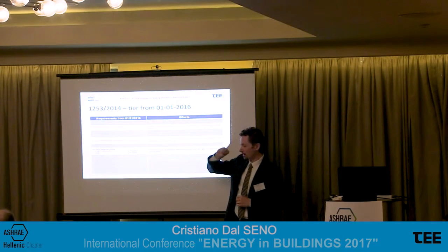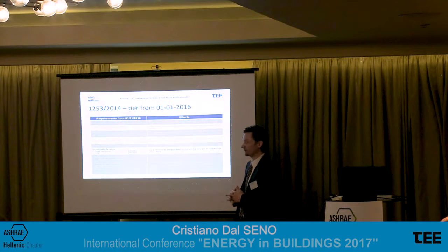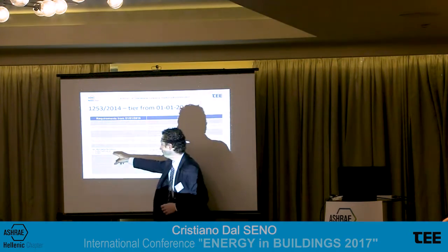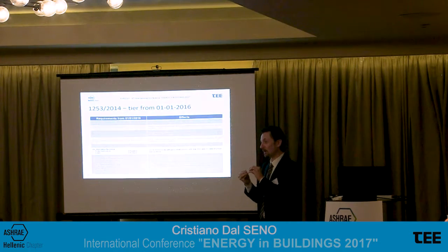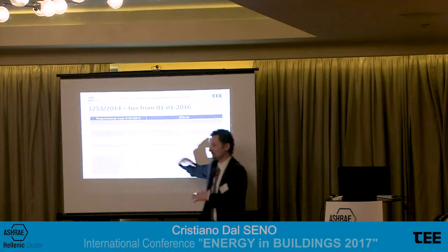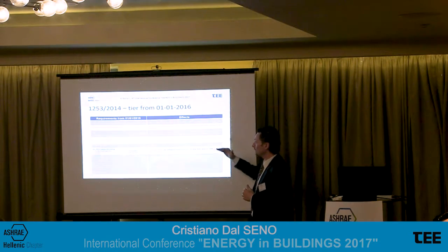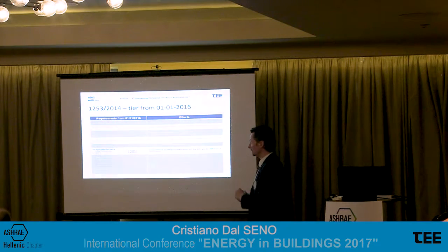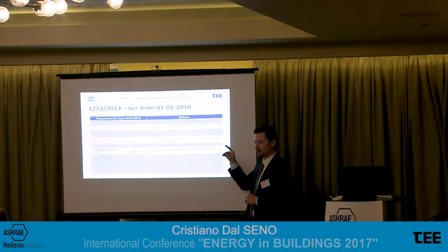When we are in installations where the electrical motor has a capacity lower than 30 kilowatts, the typical comfort application, buildings, offices and so on, we have a formula that calculates the minimum ventilation efficiency according to the capacity we apply for the electrical motor. If the electrical motor is 3 kilowatts, okay, we put 3 kilowatts. It's 4.5 kilowatts, we put 4.5 kilowatts. And we calculate the efficiency in ventilation according to the capacity of the motor we install in the unit. This value is the limit value that the unit should respect.